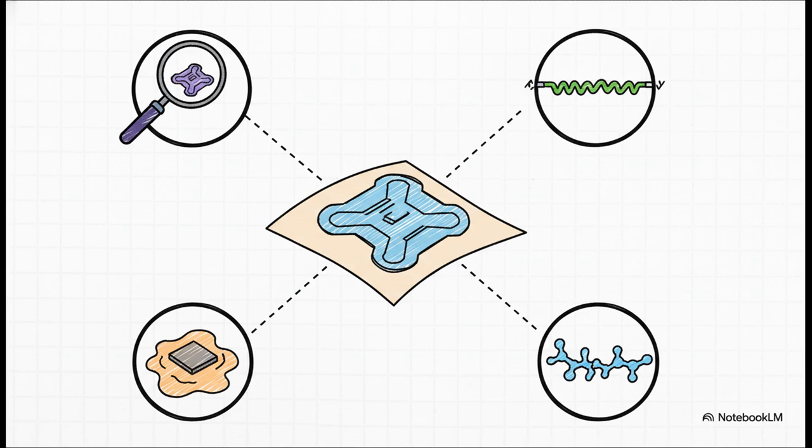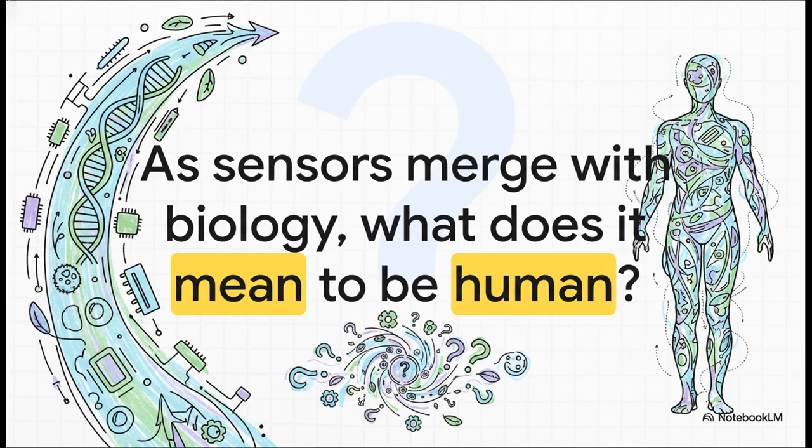We're talking about making components so small they're microscopic. That's a field called MEMS. We can build metal interconnects that are shaped like tiny springs so they can actually stretch. We can use soft gels and polymers, like PDMS, to wrap around the rigid electronics like a cushion. And we're even developing brand new organic semiconductors that are just naturally flexible, right down to the molecular level. This whole wave of innovation is paving the way for a future of seamless biointegration that could totally revolutionize medicine.